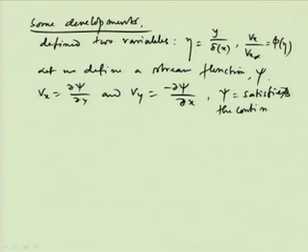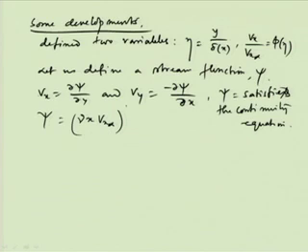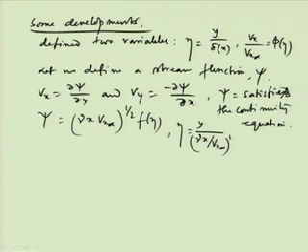Okay. Now, under that situation, psi is equal to nu into x Vx infinity whole to the power half into f of eta, where eta equals y by nu into x by Vx infinity whole to the power half, and nu is mu by rho, and x is the distance from the leading edge over the boundary plane.